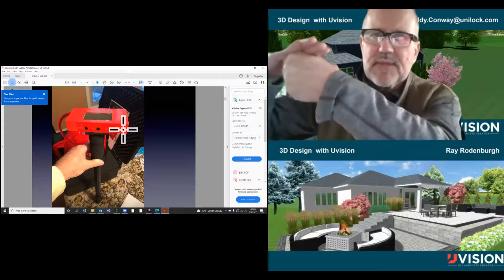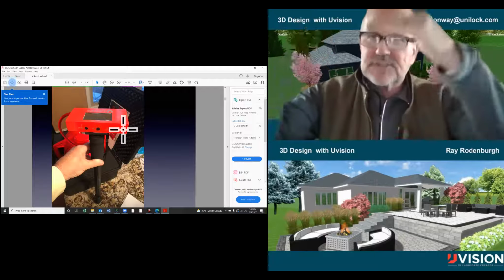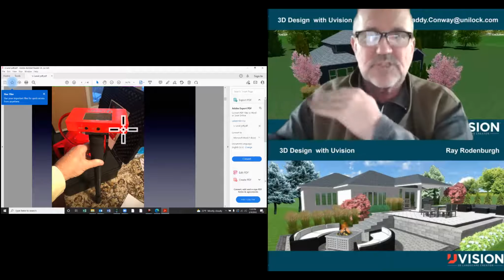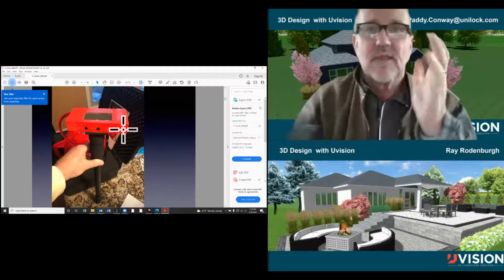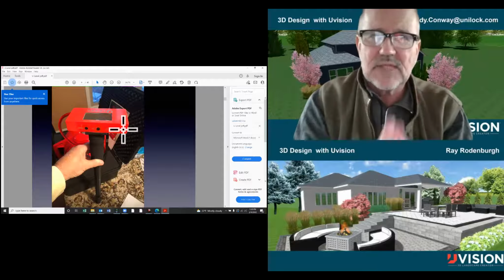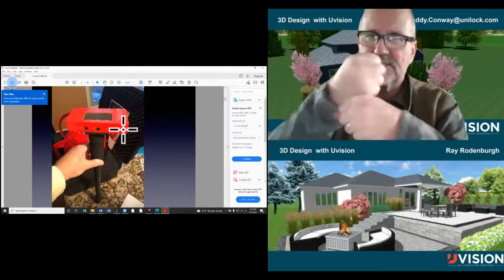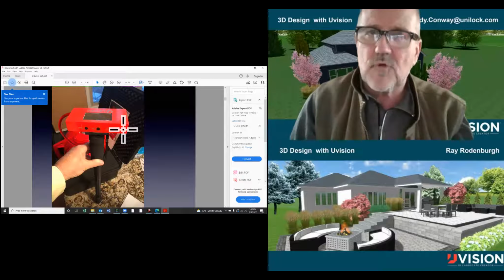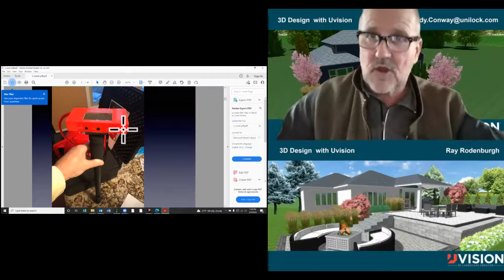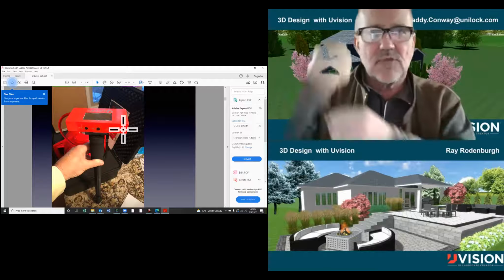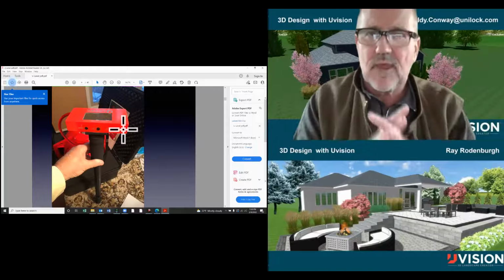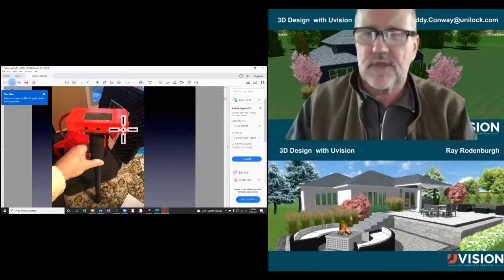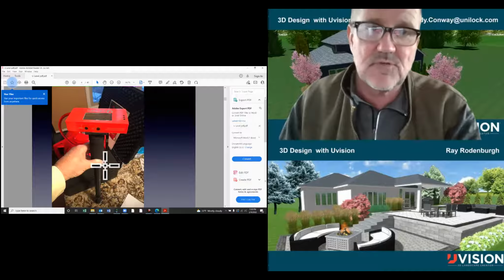Because it's up in the air, the difference in elevations between the points, which is what you're trying to get, is immaterial. As long as the pedestal does not move, you can't switch it. You can't use the pedestal and then put the device down and expect consistent readings, one or the other. I generally don't use the pedestal.